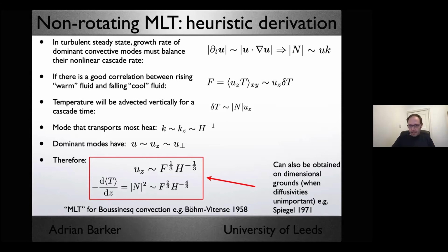What I'm discussing here is general if you fix the heat flux. But in the simulation, instead of having fixed temperature boundaries, we don't constrain the heat flux in the interior. What we're going to do is actually fix the flux. That's right. I'll discuss that in 2 slides' time when I show the model. We're going to fix the heat flux through the domain rather than the temperature difference. Excellent. Thank you.